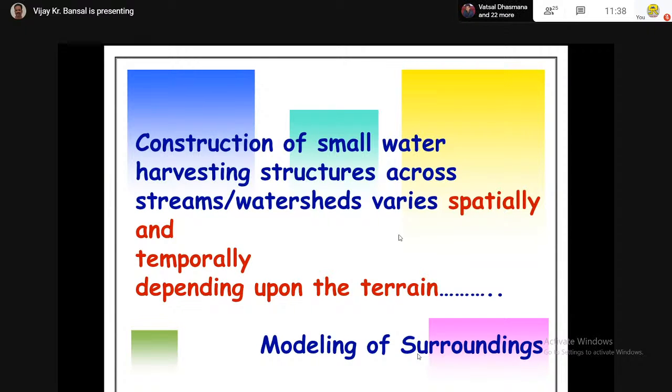This area based selection highlights all the facility components within specified distances. Then there is calculation of area and volume. You can calculate the surface area, which may be on the surface or projected area just on a plane, or the volume of cut and fill, a volume occupied between two surfaces, just like if we do excavation, or volume between a surface and the reference plane.